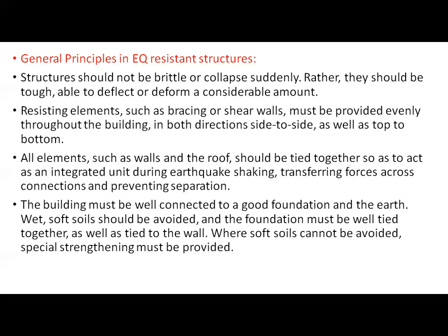All elements such as walls and roofs should be tied together so as to act as an integrated unit during earthquake shaking, transferring forces across the connections and preventing separation.